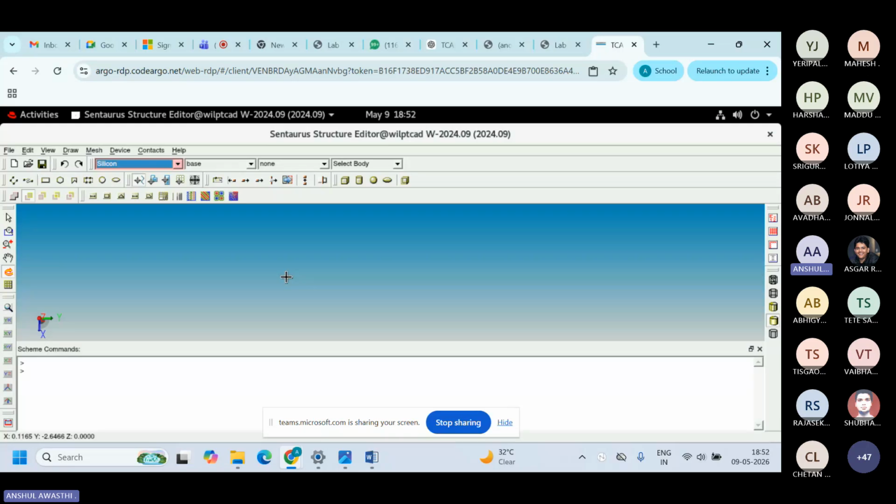And third, what is the size of the contacts we need to place? In some of the experiments, you need some extra aluminum in the contacts. In some, you directly place the contacts over silicon. That depends. In some cases, you need a thin layer of aluminum, that is metal, before placing the contact, so that proper isolation is there. We can see how to use both ways.